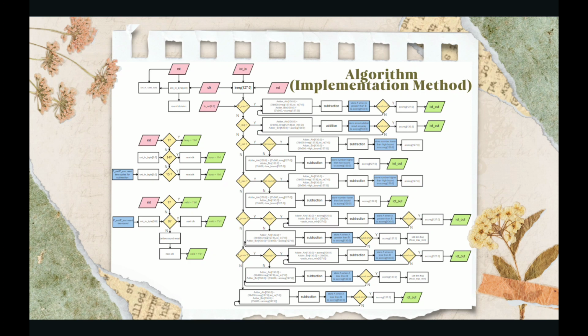For extract, we will store every number lower than the high bound and higher than the low bound into the ACC register, and then send them to the IoT outputs. Opposite to extract, exclude will store the values higher than the high bound and lower than the low bound into the ACC register. Both extract and exclude require 2 times of computation. We compute with the higher bound in one clock and then compute with the lower bound in the next clock.